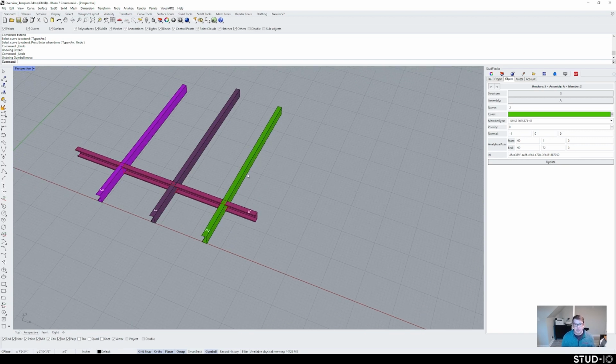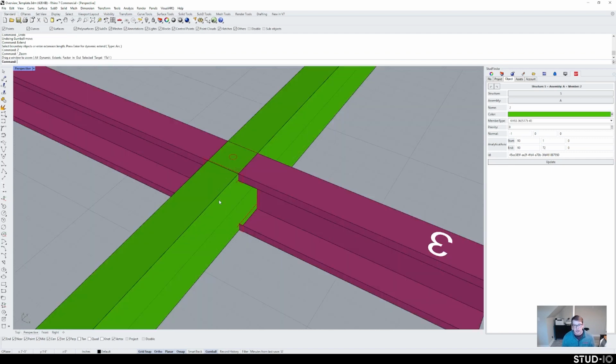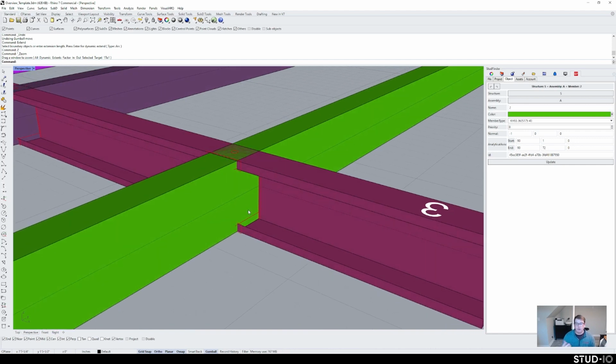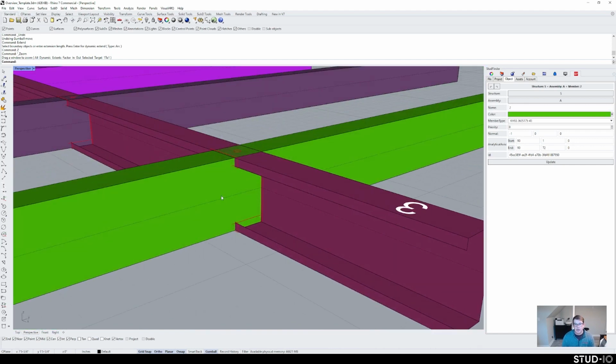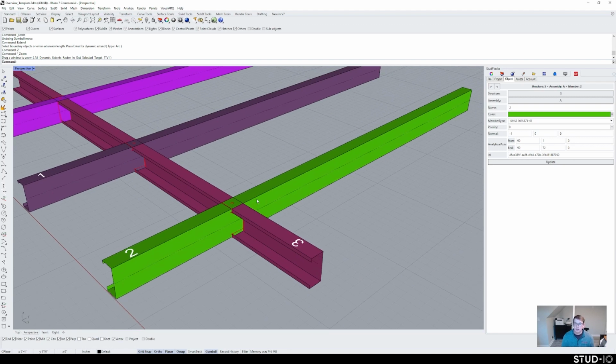And then the last thing you might want to do manually would be to add operations to a member. Of course, any member that is involved in a connection, those connection operations, what you need to actually connect this stud to that stud with alignment, so lip cutting, notching, swaging of this other stud, dimpling of both of those, are going to be connection operations, and those will get generated automatically by our solver.